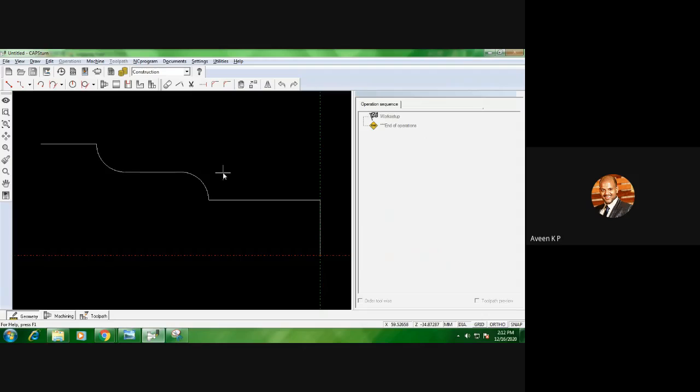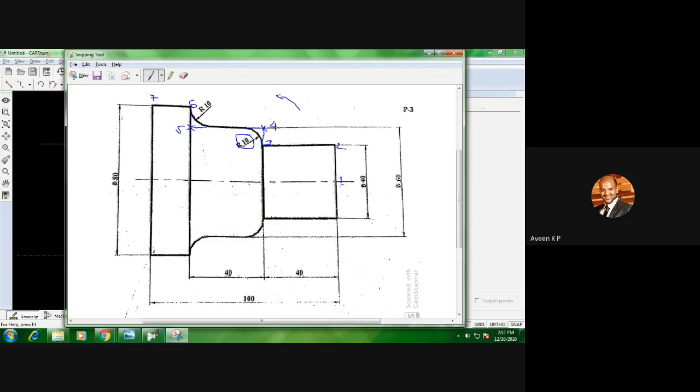Once this is done, for example, in case you have a chamfer, the same I will show here, but in the given sketch, we don't have the chamfer. In some problems, you may get the chamfer. So this particular area is not required. How to do that? Let me consider the distance given in terms of dimension and angle, that is 3 into 45 degree. So let it be the dimensions given.